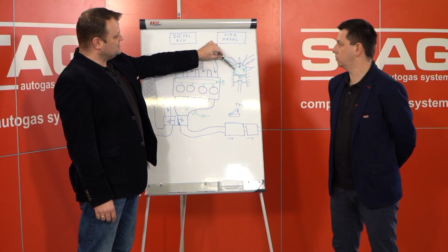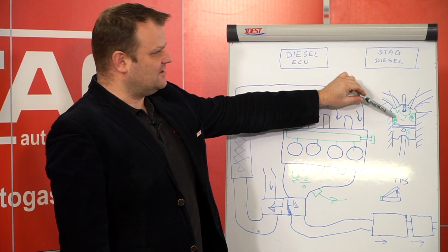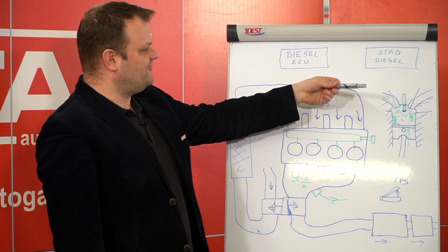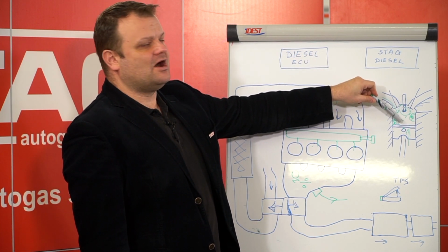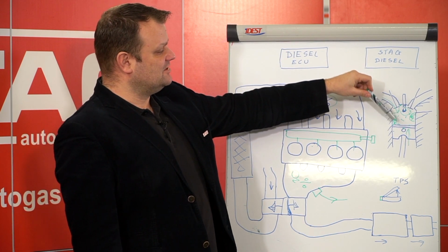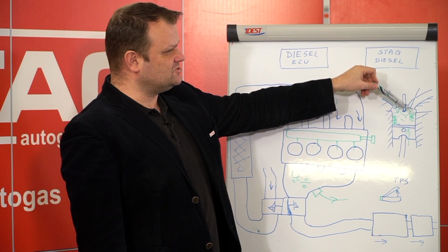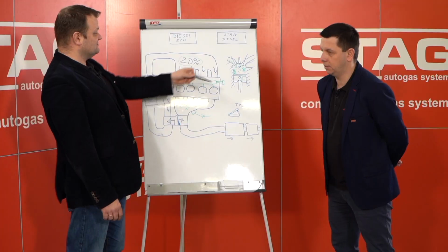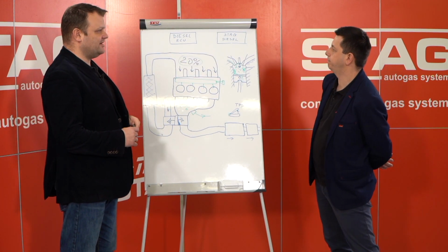Yes, there are some stratified areas in the cylinder, and these stratified areas cause uncontrolled flame starting in the cylinder. This can cause high pressure and knock, and of course the knock is a source of engine damage. It can burn some components, destroy the piston or valve or even a head, and sometimes even a cylinder can crack during a high level of knocking.